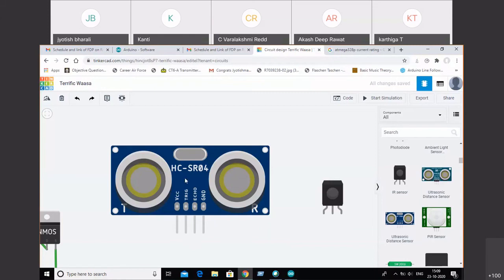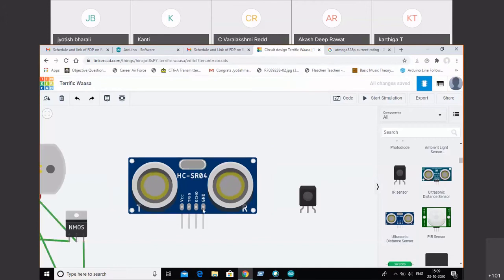What the microcontroller does is that it measures the time. You see how fast it is. It measures the time from when it has given the trigger signal to when the sound is received. It will measure the time between these two, and then it will calculate the distance based on the time taken to receive the signal. So this is the basic function.